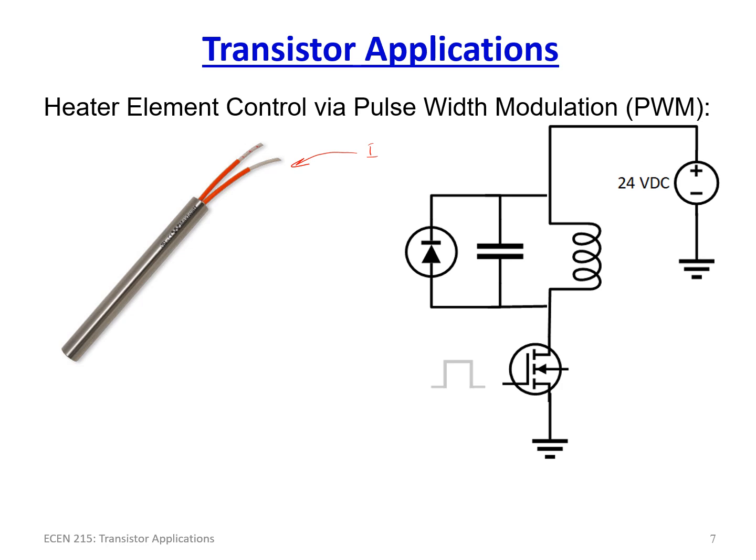In fact, it's squared proportional, because remember, power is equal to I squared R, right? Or it's also equal to V squared over R, so we can either proportionally control the voltage or proportionally control the current, and we can affect power. So we can affect the amount of heat that we're delivering to, say, a vat that we're controlling on an industrial process line. So how do we do this?